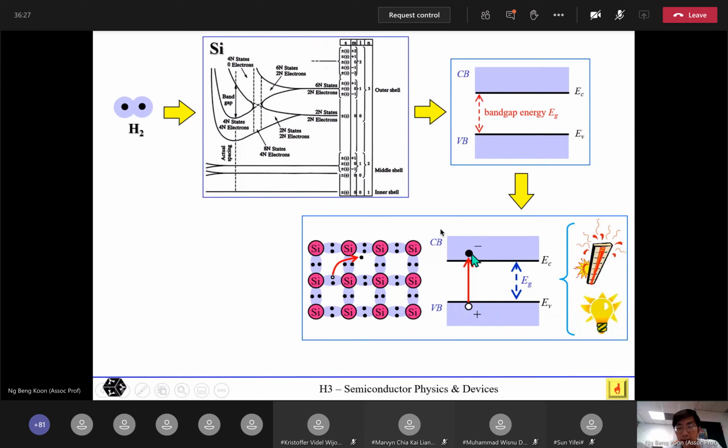In the case of the band diagram, one thing you should also take note of is that the energy band diagram is a plot of energy of electrons. The vertical axis is the energy of electrons. In other words, if you go vertical, it shows increasing energy of electrons. In the case of holes, because they're positively charged, the increasing energy for holes is actually downwards. So to a hole, if you go downwards, it's actually increasing in energy. So it's opposite, because the charge is different.